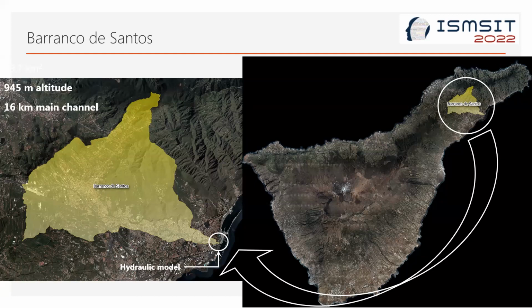From the collection of rainfall data from the mentioned date, February 2010, collected in the different rainfall stations that we find in the slope basin of the Barranco de Santos, and topographic data of a section of its main channel at the height of the Serrador Bridge, a hydraulic model has been made by means of which to simulate the theoretical height that the water sheet would reach in the section of the ravine modeled for the theoretical runoff flows obtained by the methods of the synthetic unit hydrographs of Schneider and Triangular.